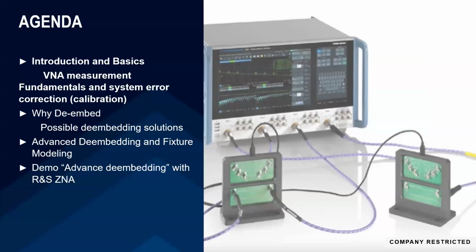Here's the agenda for our webinar today. First, we will go through the fundamentals about the vector network analyzers and the measurements that it takes. And then we will go through the system error correction or the calibration, which is one of the main topics about the VNAs. Then we will see what is de-embedding and what are the possible de-embedding solutions. After that, we will go through the advanced de-embedding techniques that Rohde and Schwarz offers. And then at the end, we will have a live demo of de-embedding a PCB structure with our vector network analyzer, ZNA.